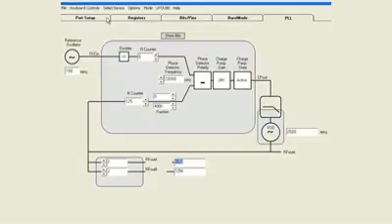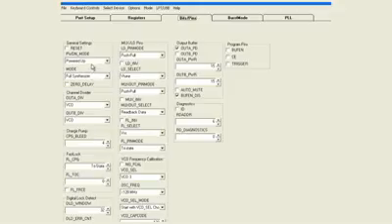But before we get too excited about hooking this up, we first have to make sure we're communicating with the device. So if we go to the port setup tab, we need to make sure we have the proper communication mode. In this case, I'm using the USB interface board. If you're using something else, be sure that that's selected. The port setup here and pin configuration is based on the evaluation board instructions. If you're having problems getting the thing running, one of the first things you should do is ensure that you're actually communicating with the device at all.